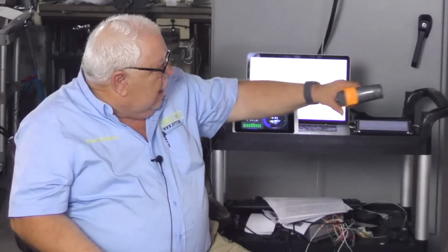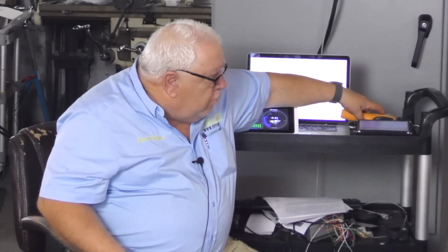This is a Fluke Model 516, and it's a reasonably accurate infrared thermometer. And I was very surprised to see the temperatures were up around 78 degrees centigrade on the top 2 modules at the terminals. This is way beyond what I want to see, and more than a tad bit alarming.